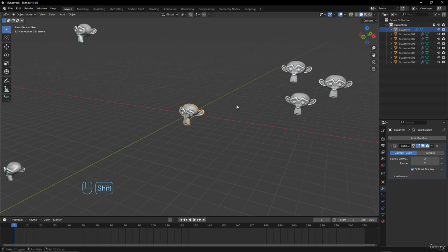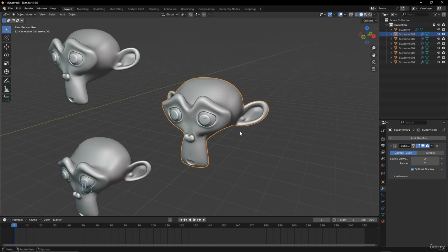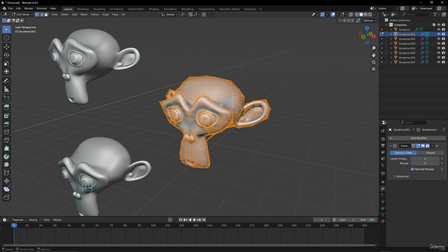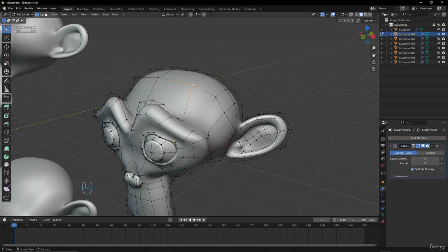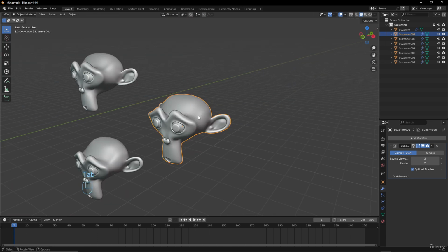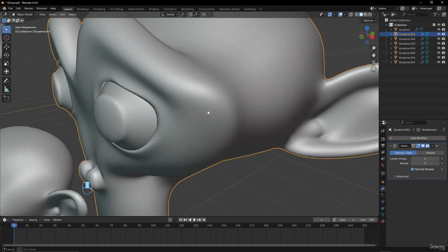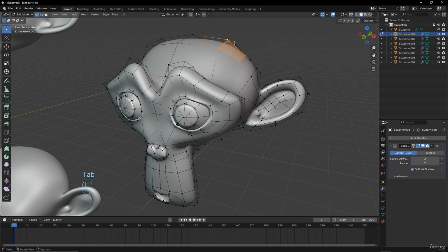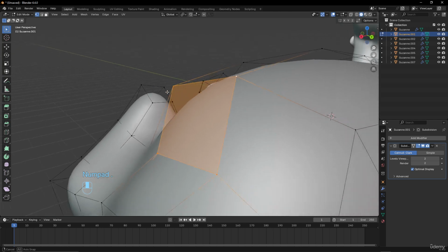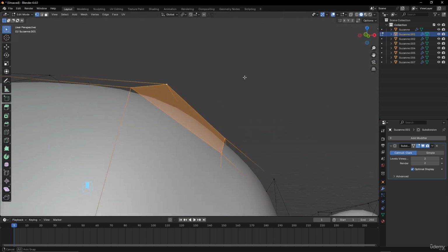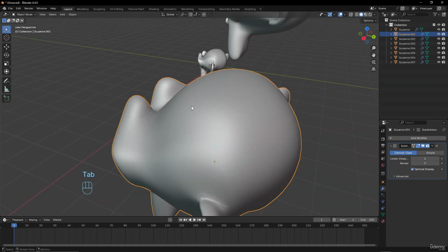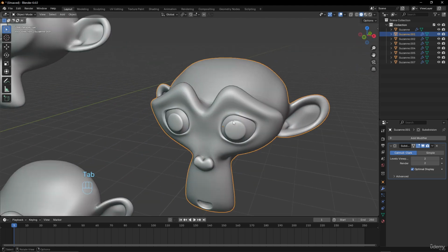It works even with other parts. Like for example, we will see the edit mode later. Okay, but in edit mode, I can select parts of the object, like for example, just this face. And if I focus on this object, when I zoom in, I'm not really where I want, okay? So I can select here in edit mode and focus on only that face. As you can see, now I turn around this face only. And it's very important to manage your view well.